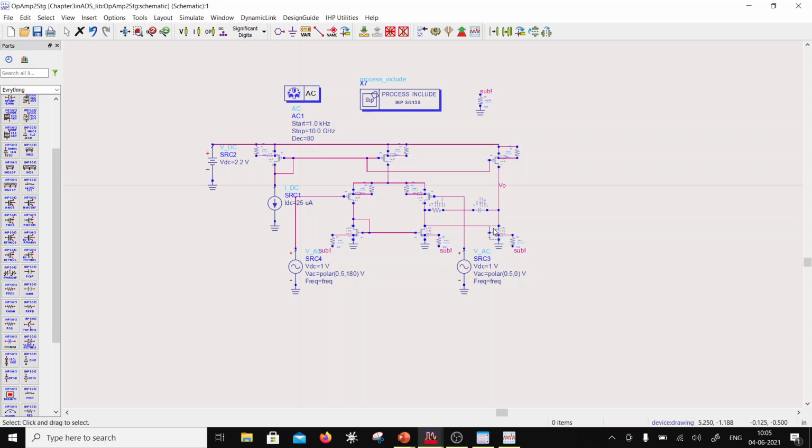You can use a cascode output stage. You can use a cascode stage over here to establish the load for these two transistors, right? So that's there. One quick way of increasing gain can be if I lower the current, the gain can go up.